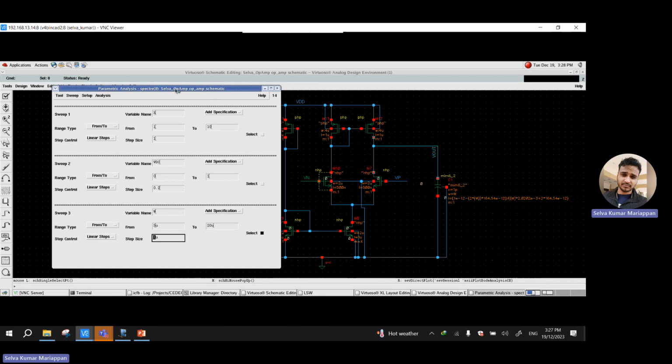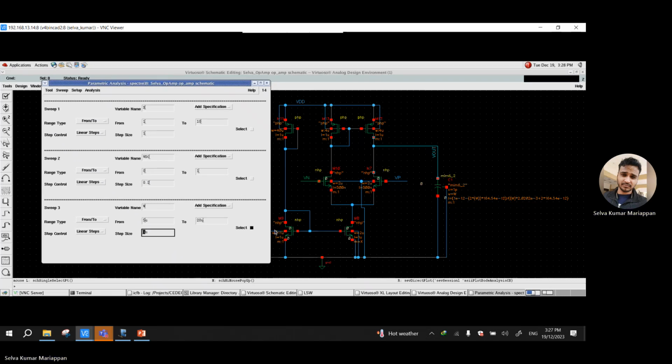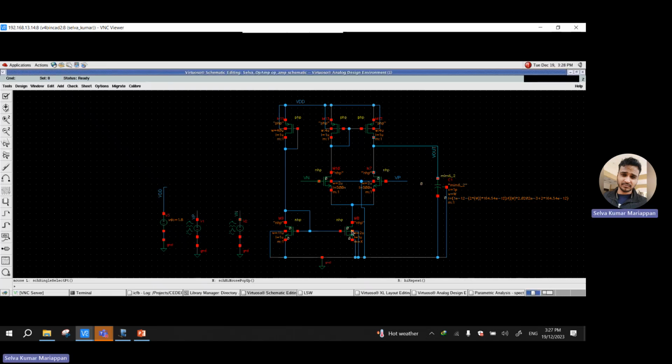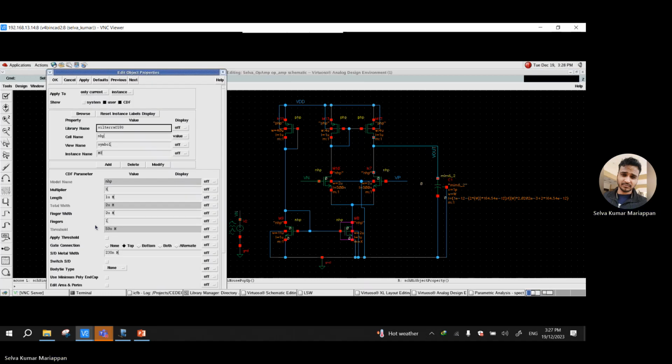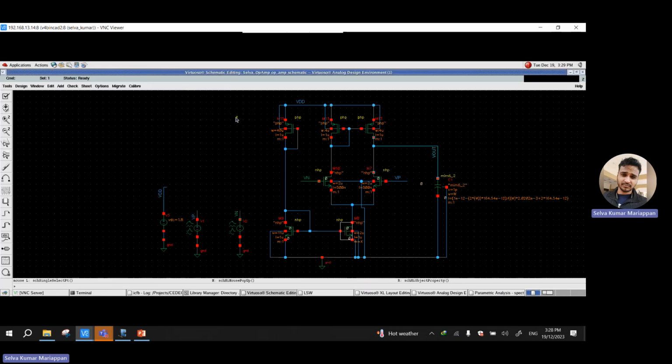So you can check for your MOSFET parameters here. You can even set your fingers, your finger width; for your length it is limited, so you can only increase the length, okay. So your multiplier, we just tested with our multiplier and we had our VDC and all that, okay. So this is for your tuning.